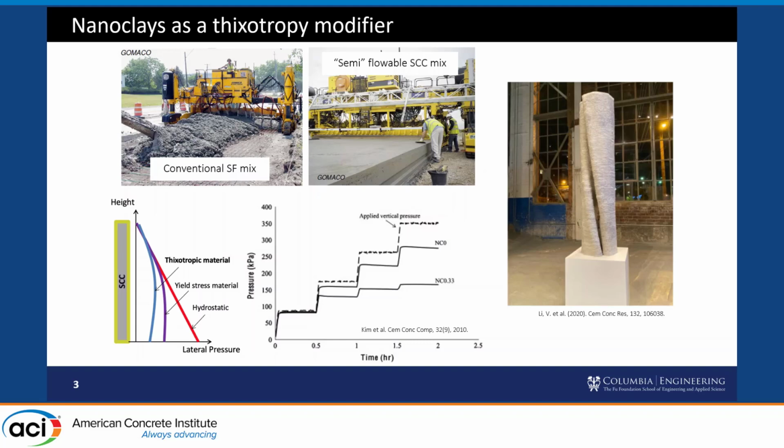Much earlier work, really pushed by Northwestern, was in facilitating different existing casting approaches. This included slip-form paving, where conventional slip-form paving requires a very, very stiff mix and intense internal vibration to achieve shape stability after extrusion, but that led to durability issues because there were trails or voids left due to those internal vibrating fingers.